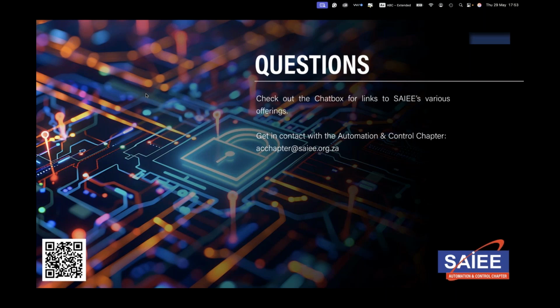Is to say, if I now have a lot of data on the field, a lot of IoTs in the field, so there's a lot of data coming from the plant, and this plant needs to reach some data repository on the IT side, and quite often the protocol that is being used there is TCP. And with TCP, the problem is it requires bidirectional communication.